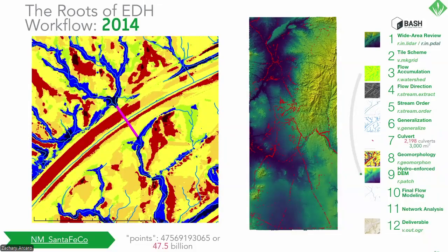Here you see blues representing valley features. So we tried to connect the upstream location of a pipe, where we had flow lines already established in blue, and the corresponding neighbor to a downstream valley location directly across the road. This worked for us about 30% of the time. Not great when you have to do more than 2,000 culverts over 3,000 square miles, but still better than nothing.